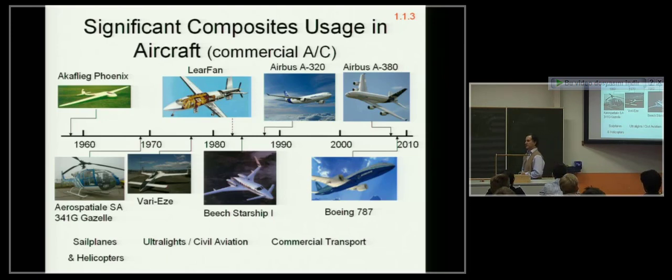Usually what happens is some manufacturer of material will come to you and will tell you, I have this new miracle material. It has happened to me a couple of times when I was in industry. And they are absolutely convinced that this material just blows everybody out of the sky. For example, when aramid came out, everybody was checking it in tension, and they found phenomenal properties in tension. So people started getting very excited, not just the manufacturers of aramid, but also the whole industry. Turned out in compression, it's the worst thing you can ever imagine. And it also turns out most aircraft structures or aerospace structures are mostly in compression. They are not as much in tension, or tension somehow you can figure out.